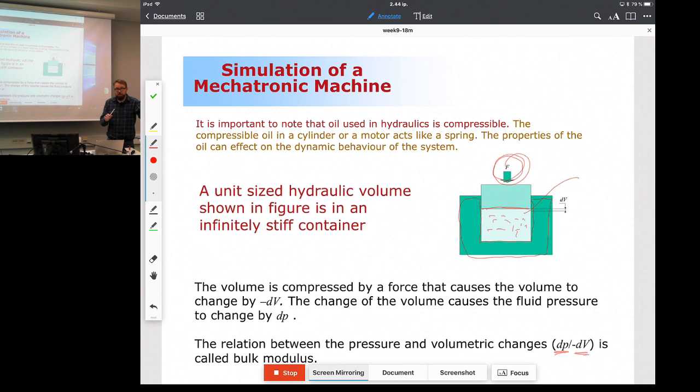What will happen inside of the pump is that the pressure will increase, but not so much, but the piston will move quite significantly. That already tells us how much more flexible air is compared to the fluid. All right, and the difference is typically like 1,000, 1,500, could be even more than that. So that's the definition of bulk modulus.